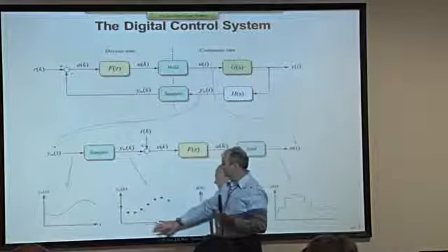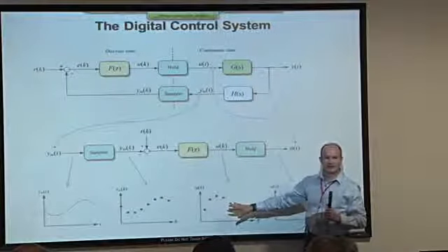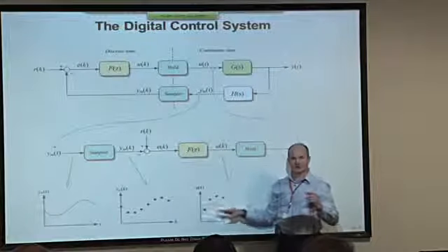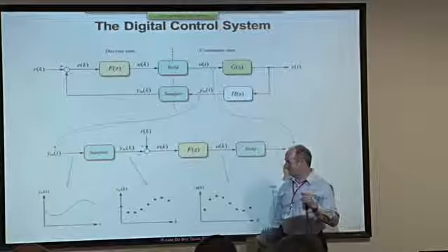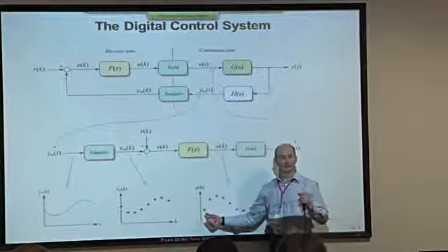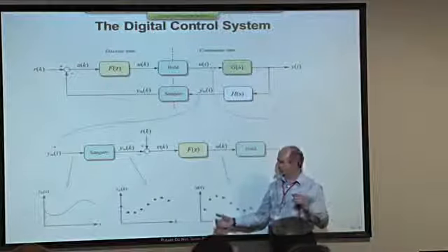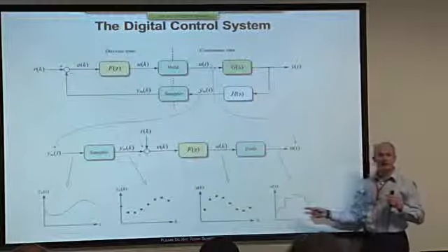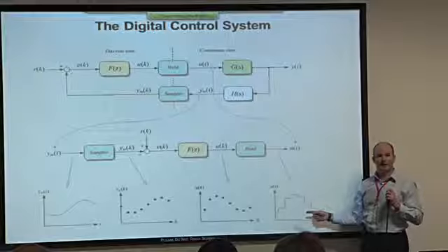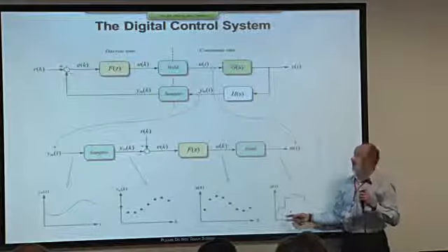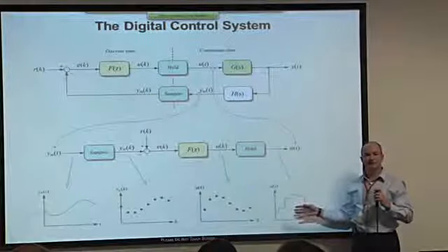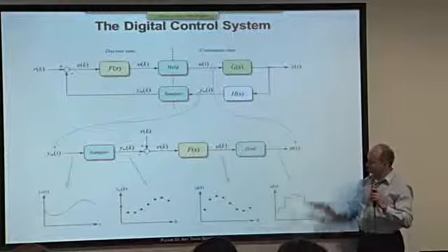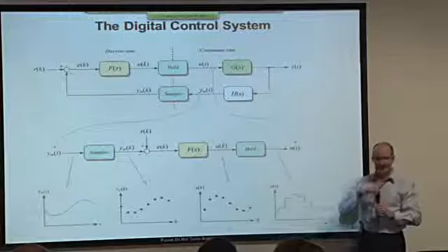It's a frequency limitation. This one, well, obviously there is a desired effect because we've designed a controller to change the dynamic properties, but there are undesired effects as well, such as time shifts, delays, and phase lags that take place. And the principal change from this one to this one is a phase lag, another phase lag. The zero-order hold reconstruction element, I've called it the hold unit, induces a phase lag as well, which is detrimental to performance. I'm going to describe each of these effects in turn.